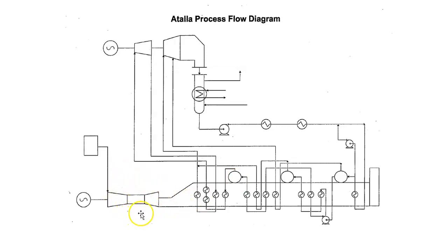This is our gas turbine. The exhaust flows this way. This is our compressor. This is the combustor where the fuel goes in, and this is the turbine. Here's our generator putting out about 170 megawatts. This is our air intake system. The air is drawn in through the compressor, and usually there's some power augmentation, such as evaporative cooling, which is basically a mist of cooling water that goes through here. So those are the basic components. We'll be seeing this again on our next exam on Friday.